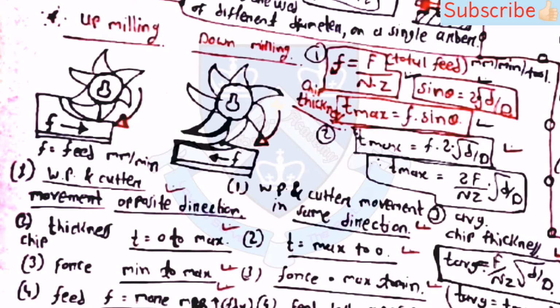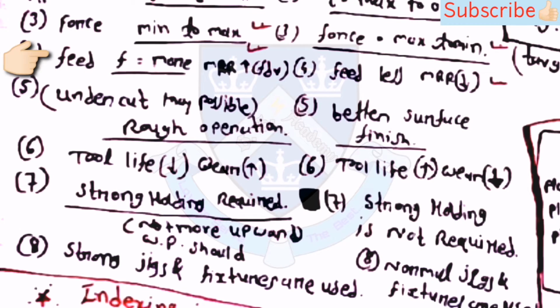For the up milling process, the workpiece and cutter movement are in opposite directions and the chip thickness is from 0 to the maximum. The force will be minimum to maximum, the feed F is more and the MRR will be more. Undercut may be possible and it is a rough operation. Tool life will be lower and wear will be higher. Strong holding is required, and strong jigs and fixtures are used for the up milling process.